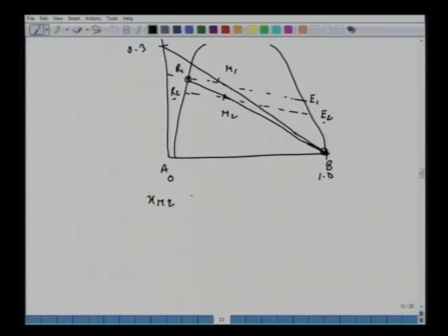All right. So this is the raffinate and E1, E2 here, and these compositions here. If you note down, this composition would be 0.095, and here this raffinate would be 0.227. All right. So again, connect this R2 to this feed phase solvent. Find the new M3 and find this tie line. This time, this point should read as 0.2, and this E3 should read as 0.078.